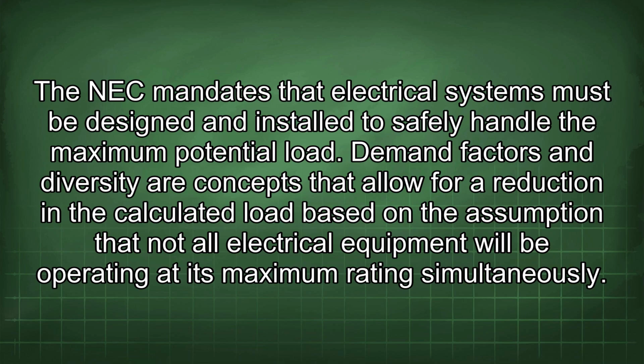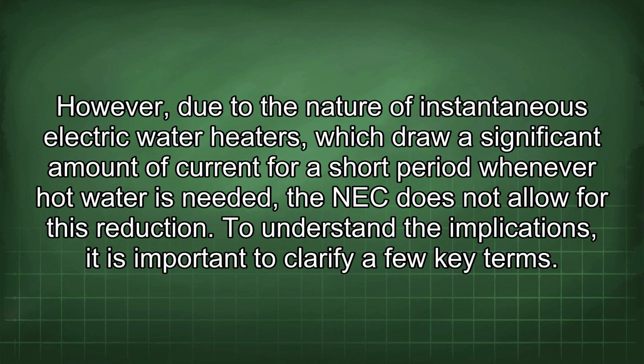The NEC mandates that electrical systems must be designed and installed to safely handle the maximum potential load. Demand factors and diversity are concepts that allow for a reduction in the calculated load based on the assumption that not all electrical equipment will be operating at its maximum rating simultaneously. However, due to the nature of instantaneous electric water heaters, which draw a significant amount of current for a short period whenever hot water is needed, the NEC does not allow for this reduction.